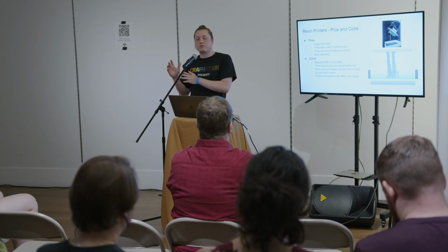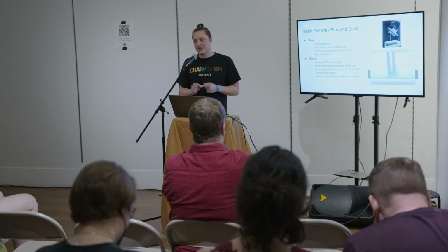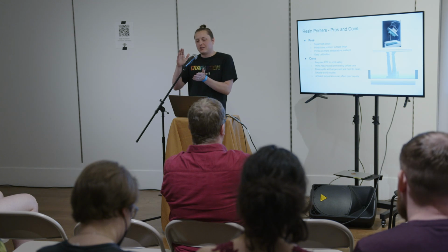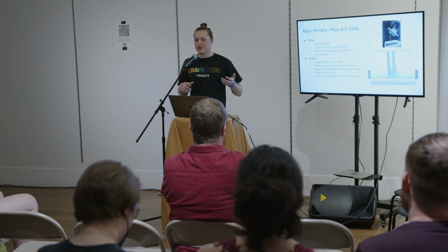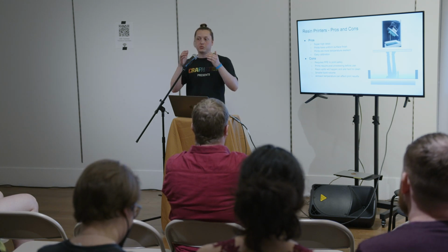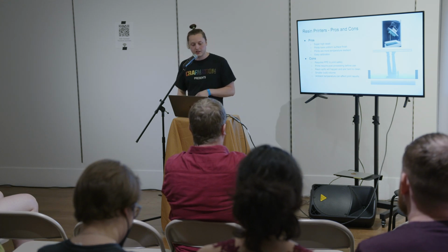After about 25-ish micron pixel size, the human eye can't really tell the difference. So hitting that 25 to 35 micron point gets you indistinguishable prints where you can't really see the lines. And there's some level of anti-aliasing that you can do, which blurs the edges a little bit to help hide the pixels, instead of having really square lines.